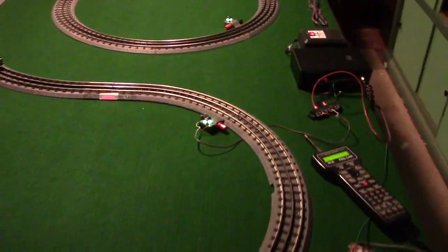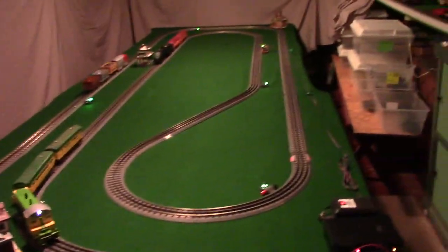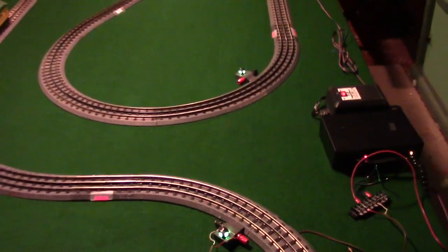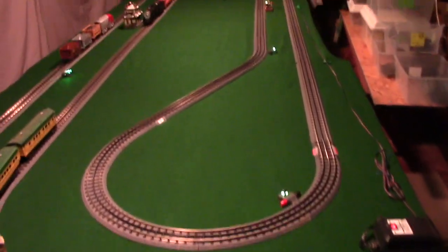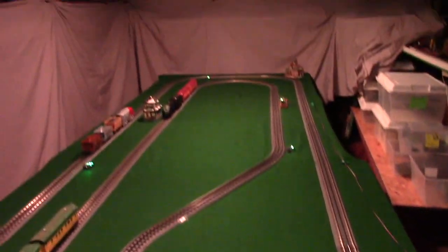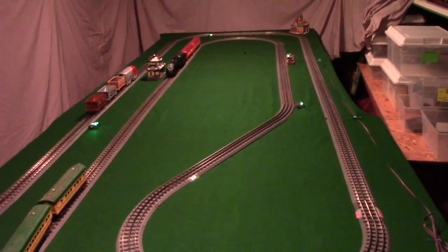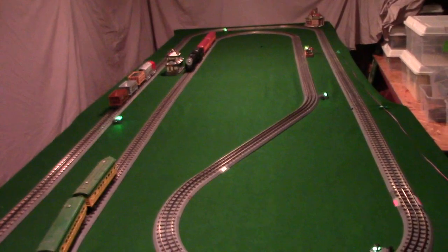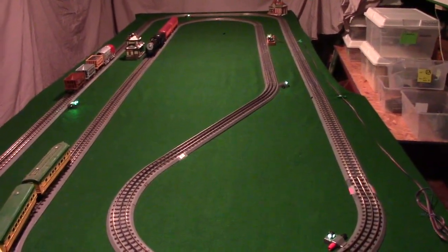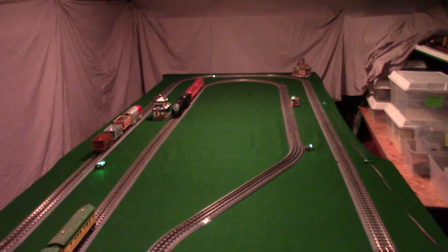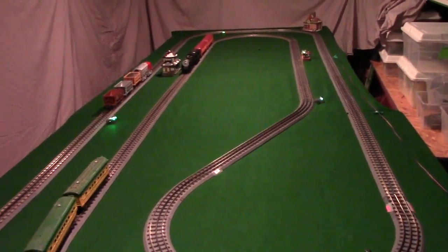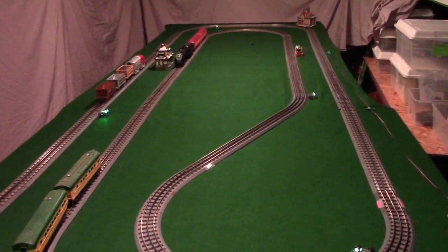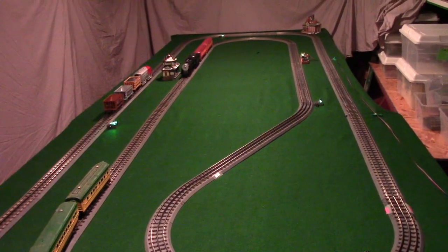And as mentioned, this is just a continuous loop of track. There's no blocks in it or anything. We've got 1 power input here, and we've got about 5 other power connections, but you can see there's no wires going to them. We can just use the lights. If the lights are on, that tells us the track is getting power there. Most people I've listened to that use the MTH real tracks, which is what this is, they sometimes have trouble losing their power. And so if one of those lights down there on the layout went out, that means I lost a connection somewhere in one of my pieces of track, and I got to go troubleshoot.